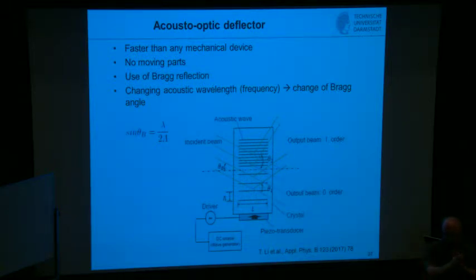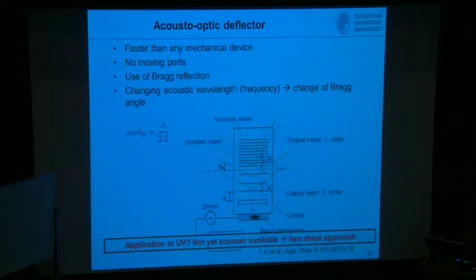So you take one PIV vector map at one location, and then within the same cycle, a crank angle or 1.5 crank angle later, in a different location. That is just one optical component in addition. So I think that's a very charming concept. It works very nicely for visible light, and currently we test that for UV.